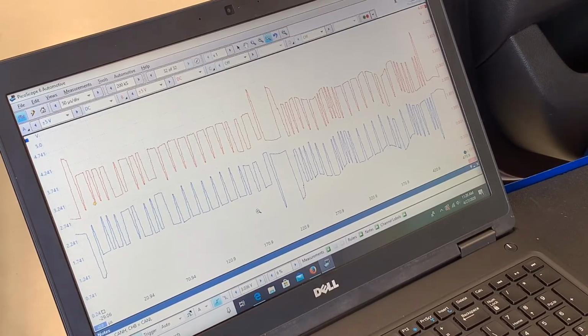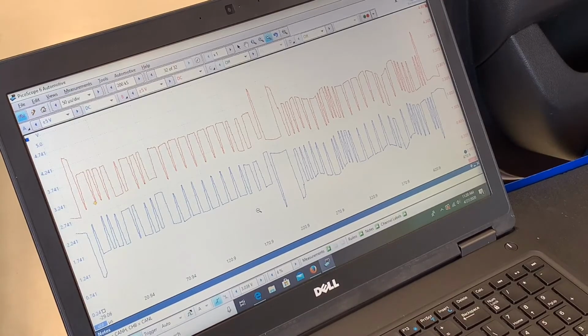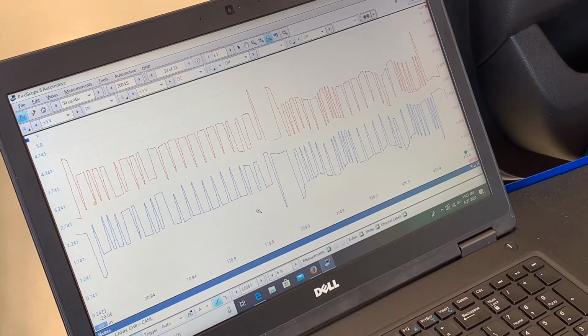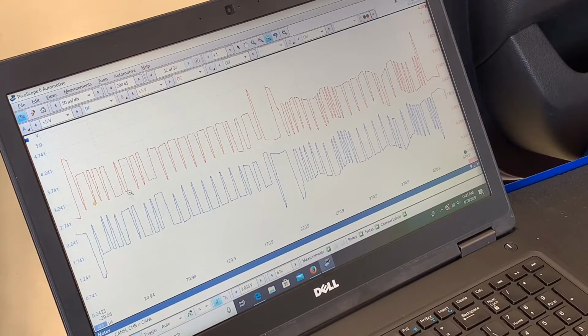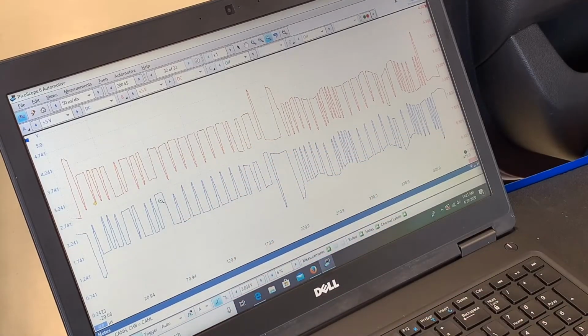So one of the challenges that I've had with this breakout box is getting a really clear cut signal. This one is not the best example, but I do have some fairly defined on-offs, which is what I'm looking for. CAN communication is a digital form of communication, and I do expect just to see on-off switching that helps transmit those packets of information. The other thing that I'm going to look for on these is that the low and the high mirror each other. I should see this repeatability as I go through that transmission.